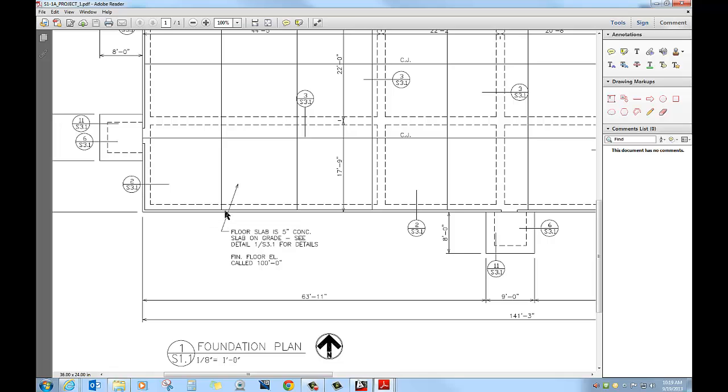This right here, these two dark lines, or two continuous lines right here, and this line here coming over this, that's an example of the concrete face edge layer. That's the edge of the concrete slab. I can see it. The dashed line, of course, is the footing that I can't see. It's underneath the whole slab. Okay. Here's a CJ. That's a control joint.